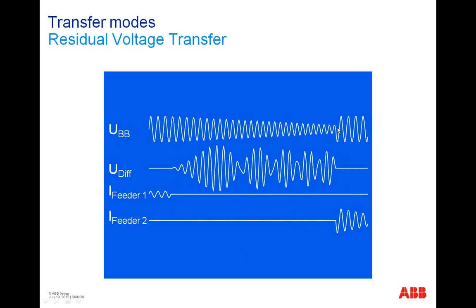Yes, frankly speaking, if we go down to 40%, then you will lose some kind of your connected loads. But this is only the transfer mode if fast transfer mode was not possible, because it is caused, for example, by a very old protection relay with a big filter time, needs a long time to detect the failure, gives the information to the SOE, the command to perform the transfer too late, and too late means the phase angle is maybe more than 20 degrees, or the busbar voltage is declining to 50% or something else.